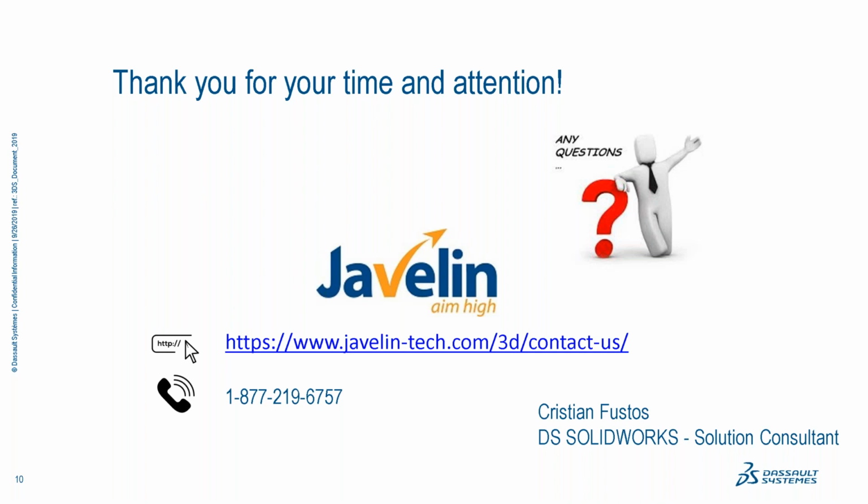So I have a question that I would like to address. We currently have a license of SQL Standard from our ERP system. Will PDM Standard, SOLIDWORKS PDM Standard, work with that? SOLIDWORKS PDM Standard is using SQL Express, and even if you do have a separate license for a higher level version of SQL, you're not going to be able to use that license. So you're going to have to use SQL Express.